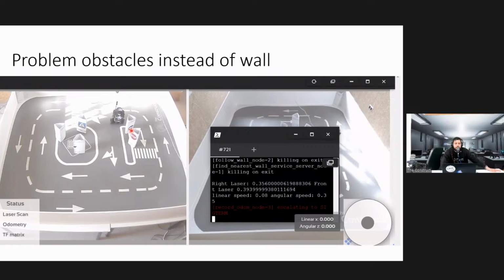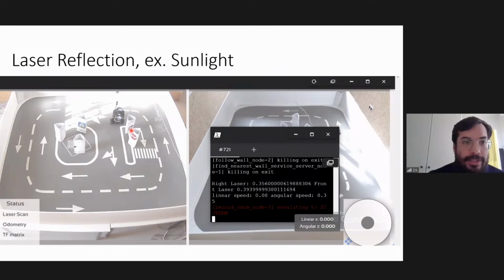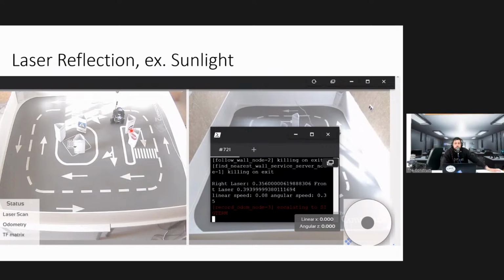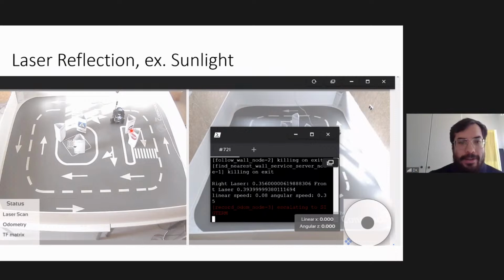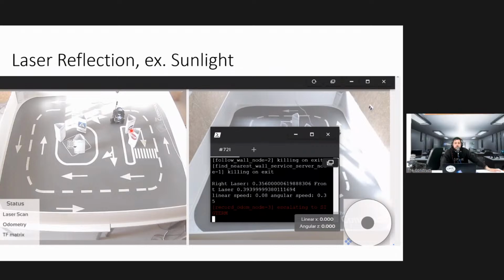Yeah, exactly. Then another issue is that, for example, when the laser dot is not good, sunlight can reflect the laser, so you don't have clear data. That's basically a huge issue, which also happens sometimes in installations. For example, AGVs, these mobile robots that do packaging, moving around, often have problems in installations when the windows are not closed.